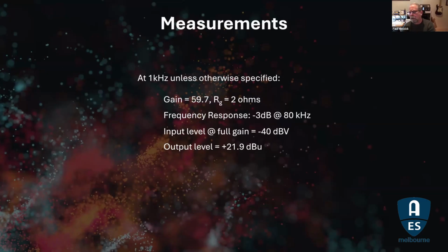with the older gear, you were driving power into a known impedance. It's 600 ohms here. But with newer gear, what you have is a low drive impedance and a high load impedance. So if the output of your device is an impedance of, say, less than 100 ohms, and your input impedance is 22K or something like that, power is not an issue here.